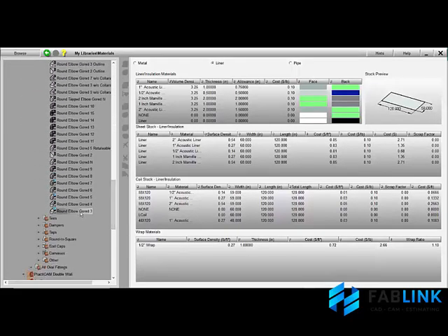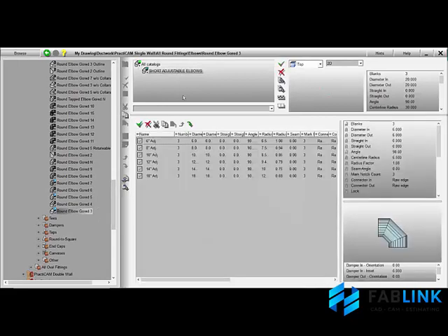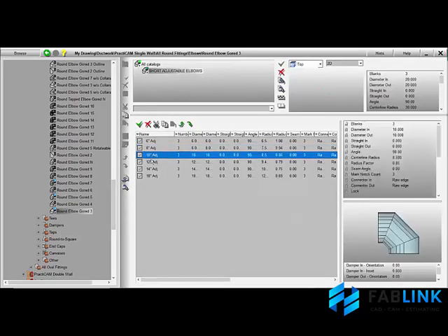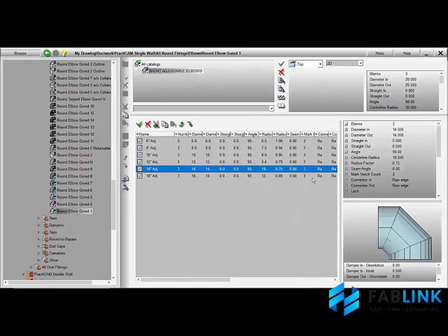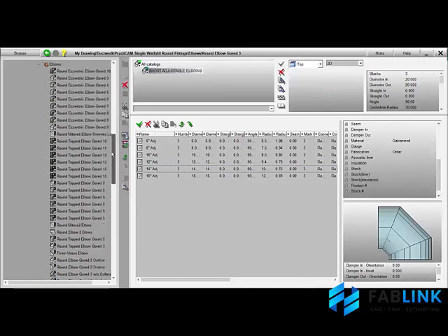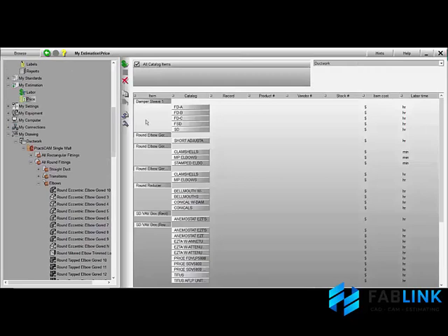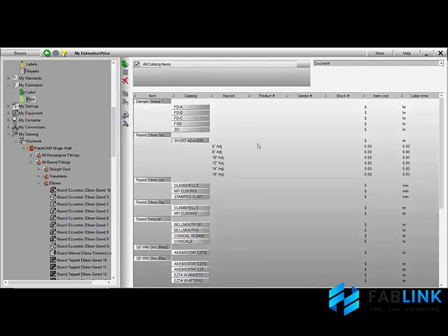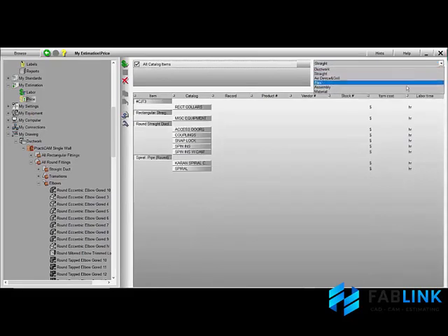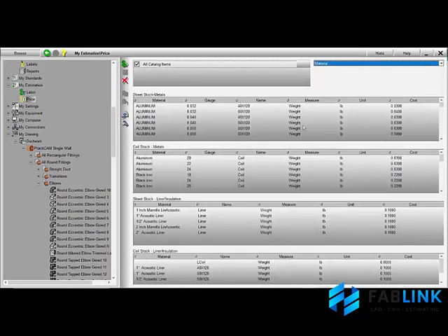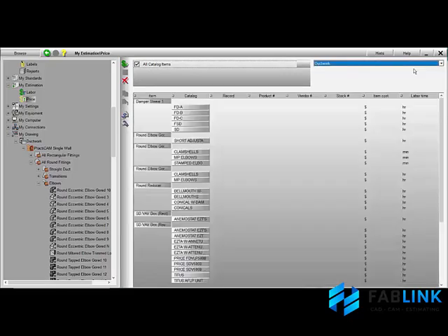See here how we have created a short adjustable elbow catalog out of a PractiCAM elbow, sizes 6 through 18. Now those that can be fabricated with PractiCAM, notice here on the right we have marked each of these items as ordered. When an item is marked ordered, which indicates a purchased item, we send everything to a centralized pricing database in the software where we can price each item out for both item cost and labor time, as you see here. This goes for straight ducts and fittings, assemblies, catalog items, GRDs, flex, and more.